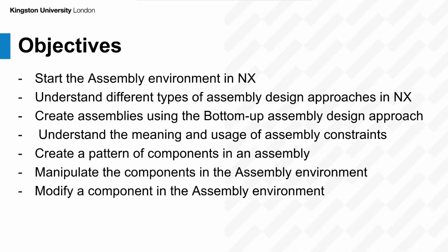Also, I'm going to talk about using the pattern features to make a pattern between different components, constraints that you already made using assembly, to make it easier and faster to do. Also, we're going to see how we'll be able to modify the components as well as manipulate them using the assembly side of the Siemens NX.